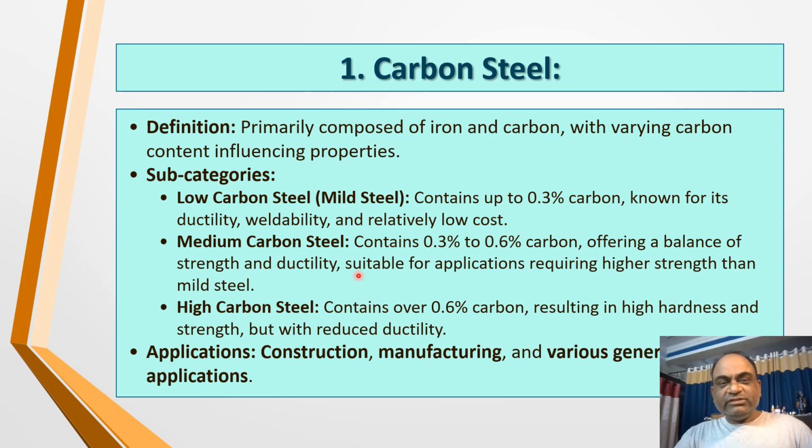Medium carbon steel, at the same time, contains 0.3% to 0.6% carbon, offering a balance of strength and ductility, suitable for applications requiring higher strength than mild steel.